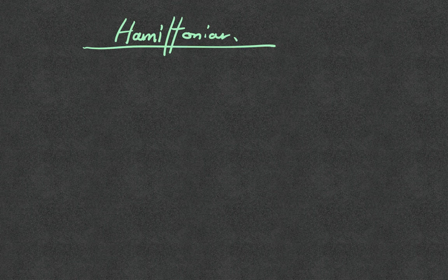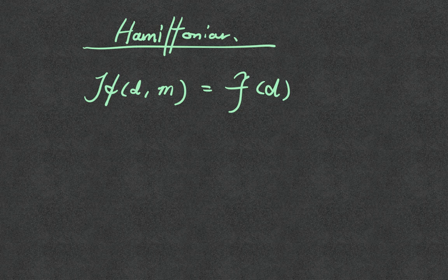What I need to do is the following. I will define something called, in this case, a Hamiltonian. Actually, you can also call it Lagrangian. We are not solving any dynamic problem. A Hamiltonian is a specific energy functional that yields the governing equations. Let me call this thing M. I write the new energy functional that has the original unconstrained energy functional part, just the elastic energy, and I would add M times G(D).